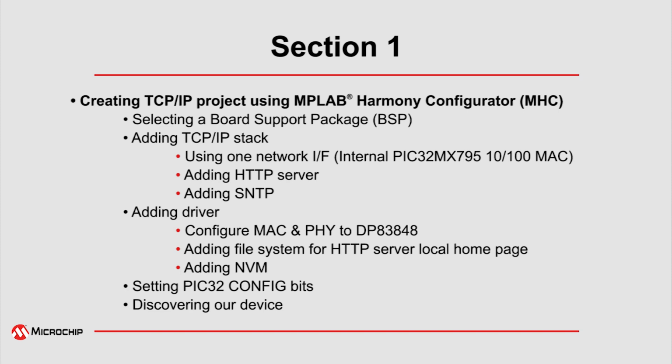PIC32. We will then be setting the PIC32 config bits with the various values for the operating mode of the device. And we will be using a utility to discover our device once it is connected to our local area network. Okay, let's start MPLAB X.